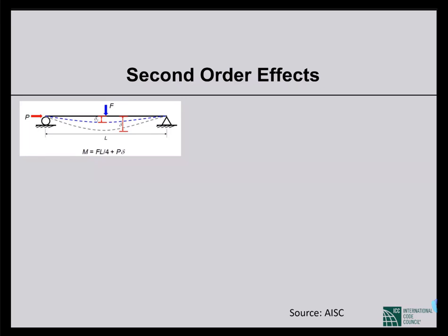So this is called P delta effect. Now, to consider this, we cannot apply the equilibrium condition on the undeformed shape. We have to consider the deflected shape, and then if we apply the equilibrium condition, only then we can consider this P delta effect, P small delta effect, or secondary moment, the effect of the secondary moment. So that causes our analysis to be non-linear.